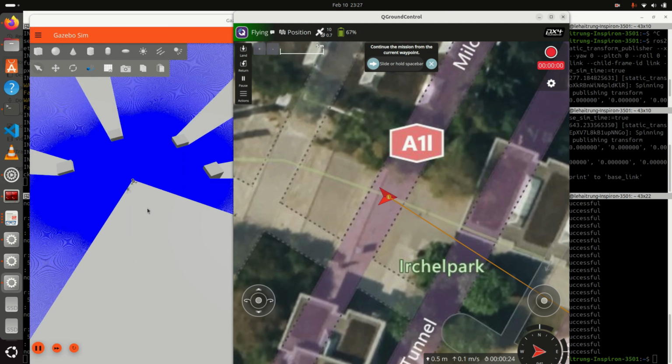Okay, you can see the obstacle now. That's good, just a bit more. Okay, perfect. Now you can see in RViz, if you fix the map to odom, you can see that the drone is flying here. This is the starting position, and this is the obstacle that we put in here. And you can see that the laser scan is changing with time also.